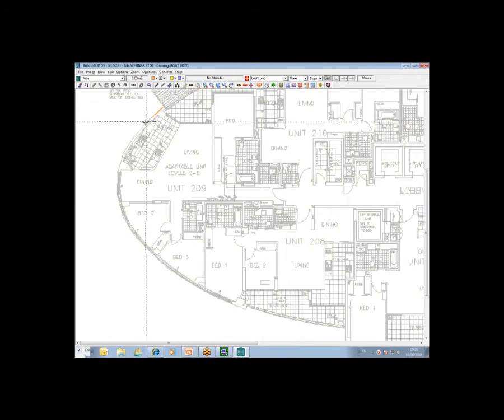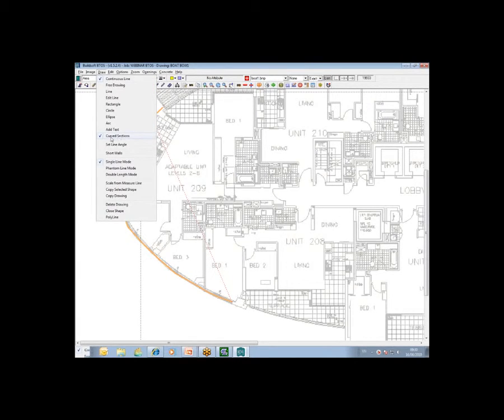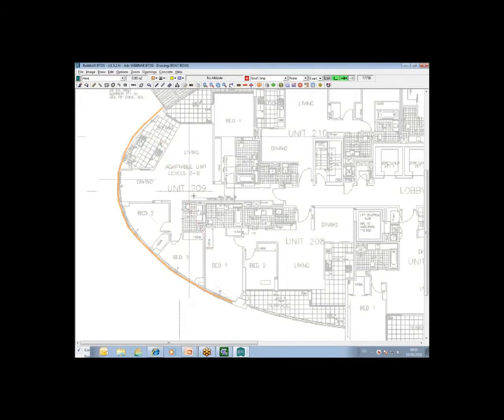Again, I start my curved section, and I'm going to do this very quickly, not to waste time. And when I'm done with my curved section, I go to my draw menu and I turn off curved section. And then I continue with the remainder of the area. And then once I get to join my first point to last, I hit J. But what you'll see has happened there is that the curved section of the area still has one dim.